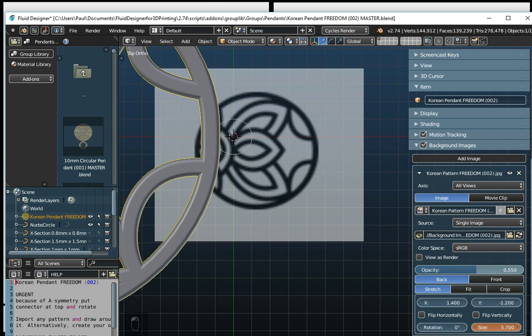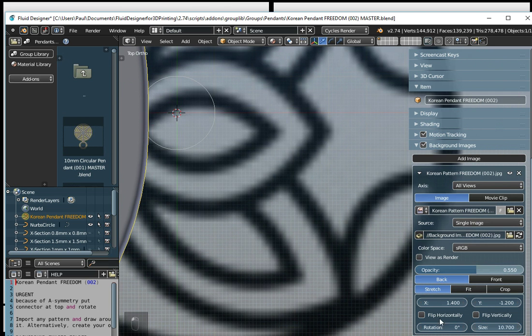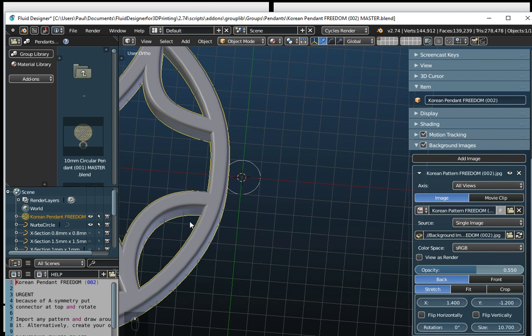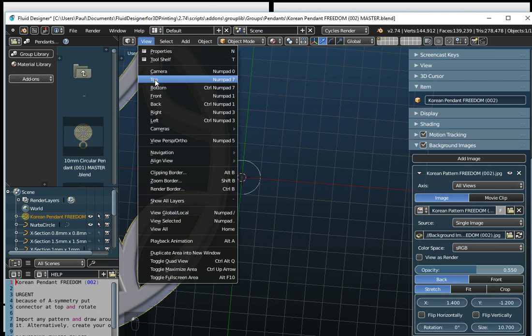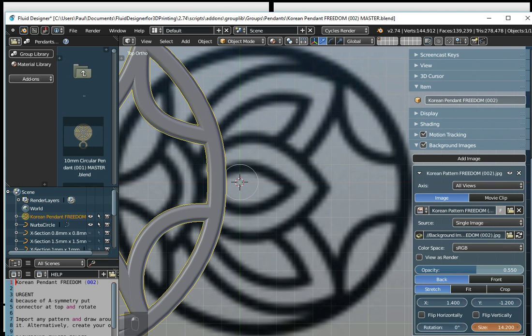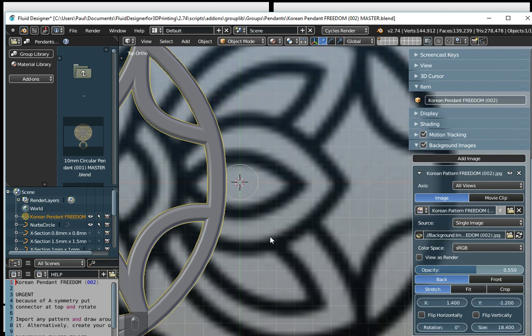So you can see if we're there, the thickness of the black line is much too small for 1 millimeter. When we're there, that's millimeters. In fact, I think, yeah, that's 1 millimeter there. So each of these boxes is 1 millimeter, so you need to size this up until the thickness of the black line is approximately 1 millimeter.